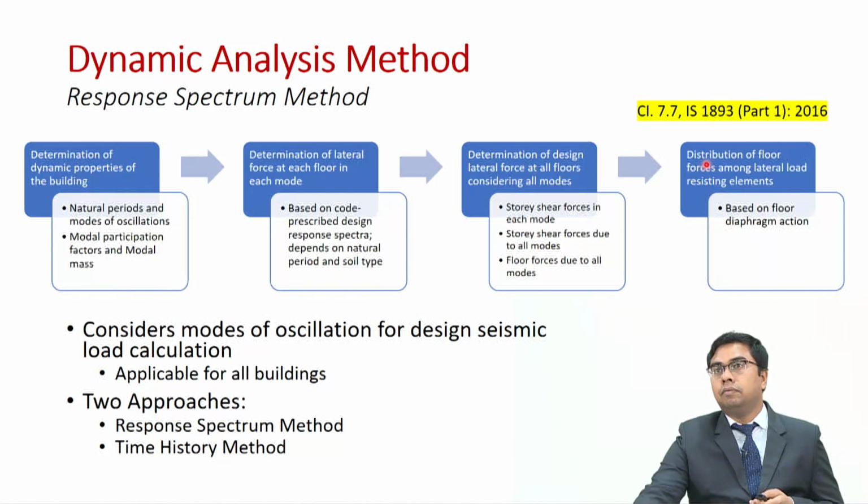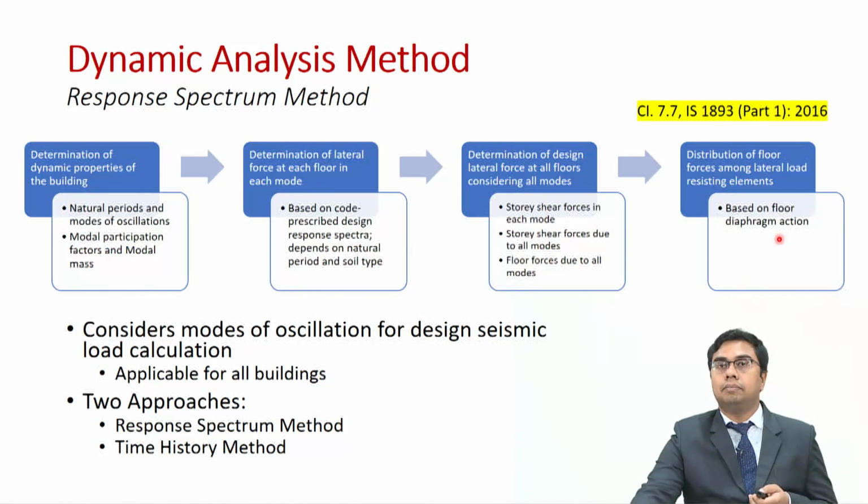Then after that we shall distribute the floor forces among various lateral load resisting elements based on floor diaphragm action, whether the slab is able to provide a rigid diaphragm action or a flexible diaphragm action.